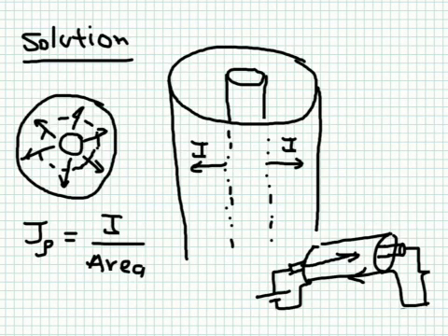So now how do you solve this problem? We can try to look at it from the top view. If we take a look at this conductor from the top, you see the figure to the left: the inner conductor, the outer conductor, and current flowing from the inner conductor to the outer conductor. This current is very weak relative to the current flowing inside the conductor, but we want to calculate it. If I call this current I, it flows radially and must be symmetric, so it only varies with ρ. The current itself does not vary; it is the same. What will vary is the current density.